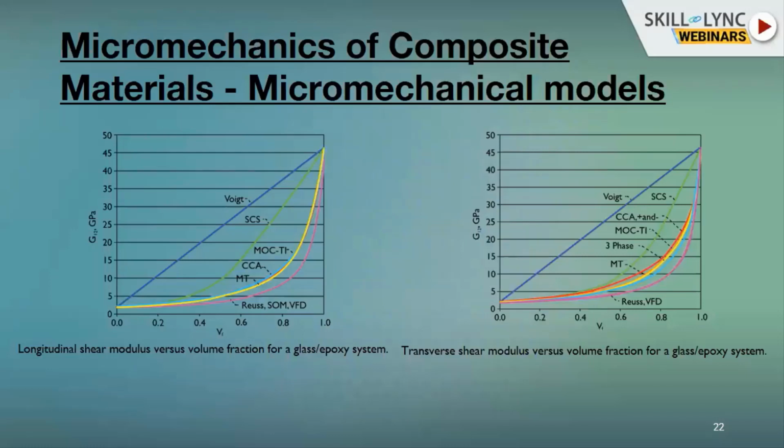So these are basically the bounds that will give you the elastic properties. Similarly, these are just a few of the properties that are shown, whereas with micromechanical models you can also get some of the strength-based properties, as well as analyze the failure and the mechanisms involved in the failure, which will help in designing the composite as well as enabling individuals to improve the designs.